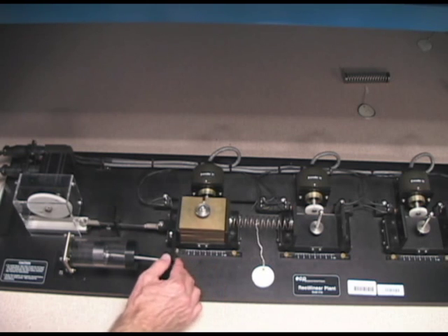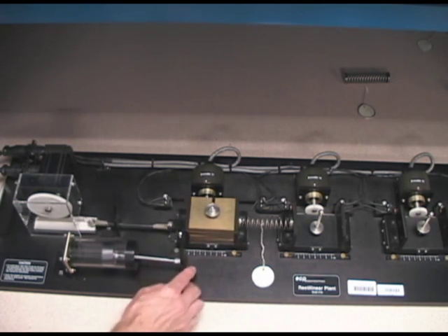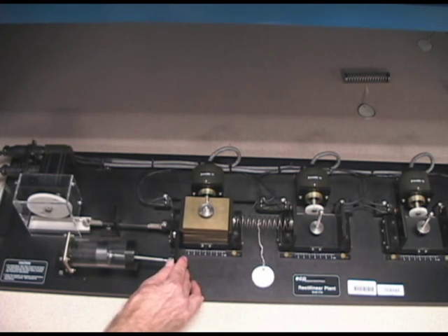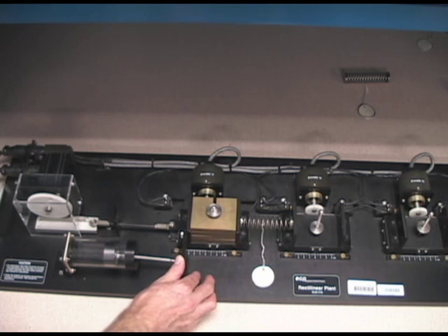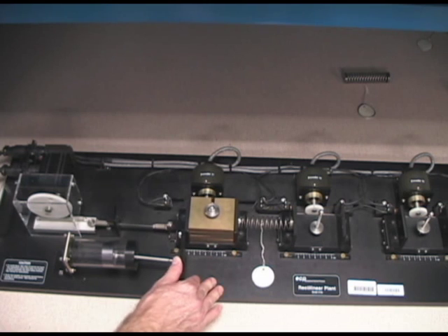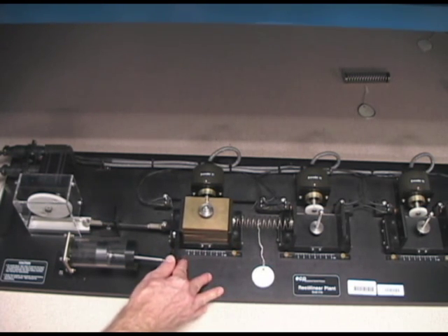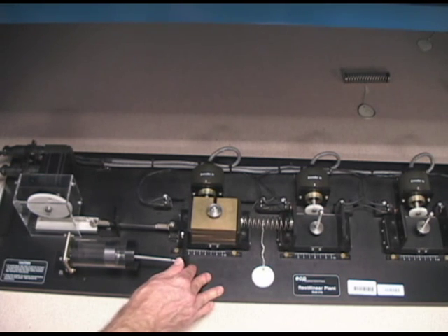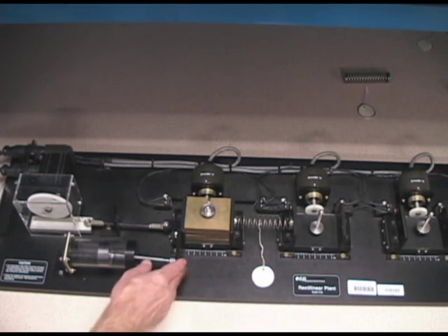But before we get there, you might just note that there is a scale on this mass. We will be commanding the mass to go roughly from the 0 mark here to a little beyond 1 centimeter. 1 centimeter in this system corresponds to roughly 1,600 counts, and we are going to command the system to go to 2,000 counts, come back and hold that for about 3 seconds, go back to 2,000, etc., and we'll repeat that process 3 times. That's where we're going.